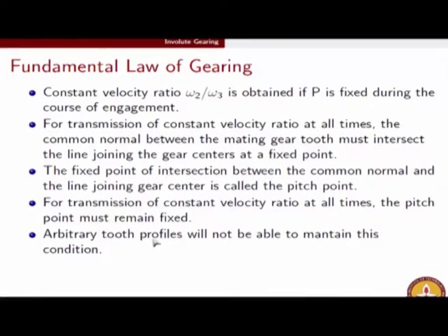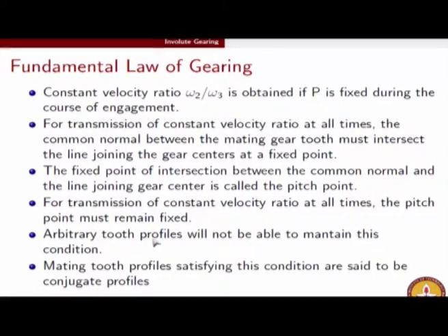In fact, a straight tooth profile will have lots more problems, but at least one very important problem is that it will not be able to transmit a constant velocity ratio, because when it is engaging, the pitch point, or the relative instantaneous center between 2 such gears cut in the manner of straight teeth, will not be maintained constant during the entire course of engagement, and that is why straight tooth profiles will not be allowed.